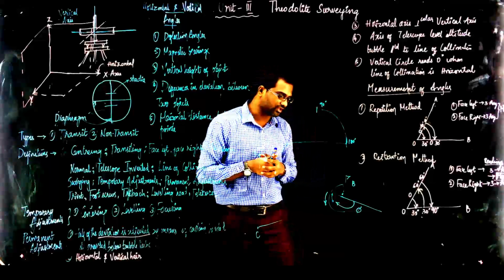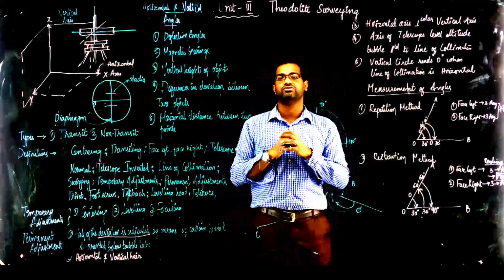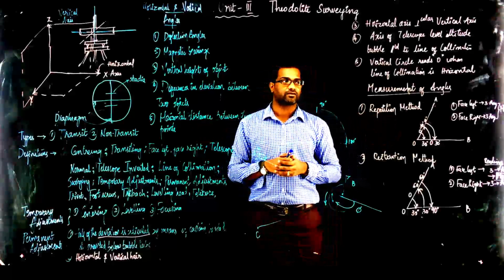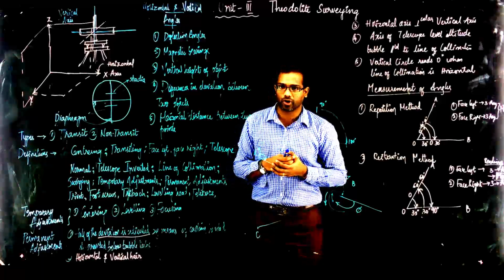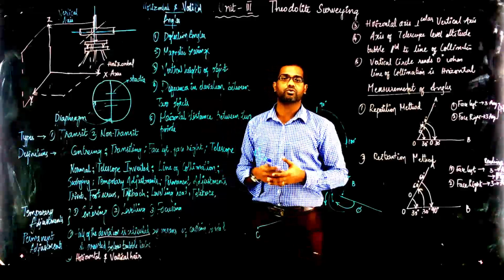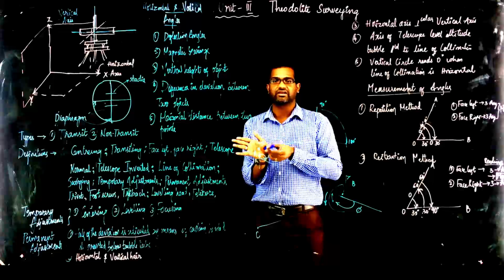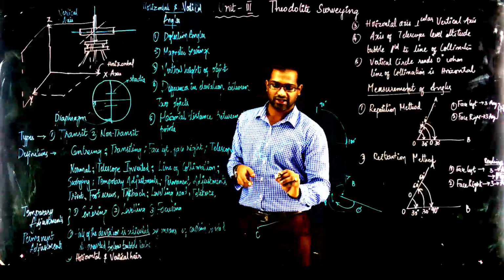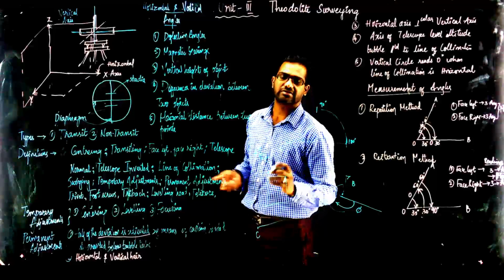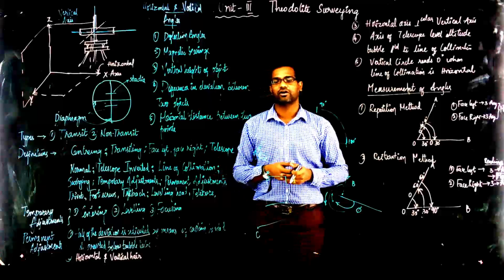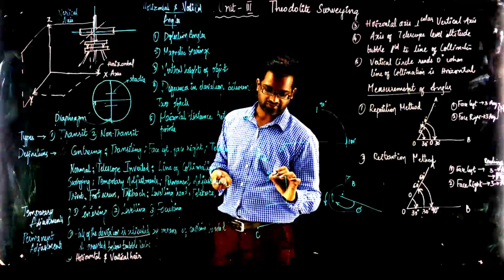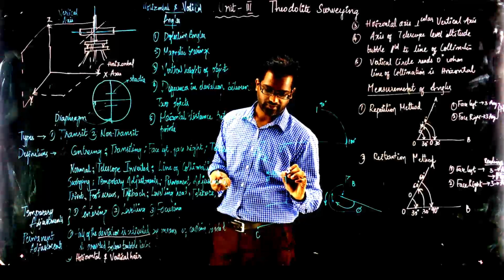So the theodolite is a very good instrument which covers the entire field of surveying, where we can accurately set out a point at a required angle. For example, to lay out buildings, we use 90 degrees, right? Exactly, the angles could be 90 degrees. If I want to set up a building, and say it is 30 meters or within the tape limit, we can easily plot it. But what if this building is 300 meters?